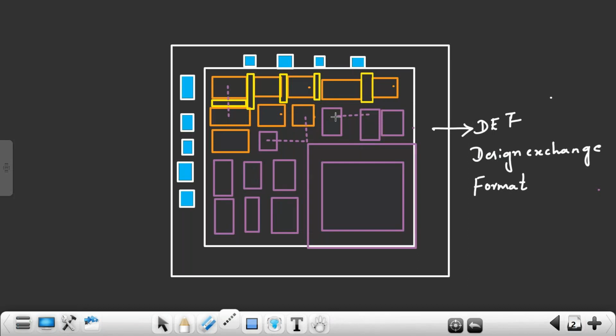Sir, after the floor plan is provided, there will be some amount of cells we'll be adding after place, clock, and route. Those are ECOs, extra cells. Yes. So we will be leaving that much space in the floor plan itself, right?